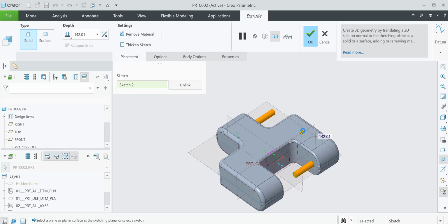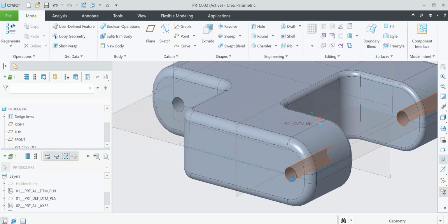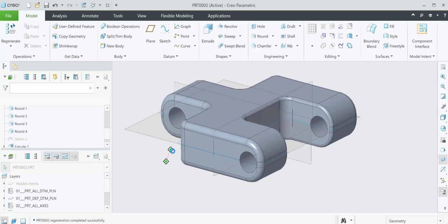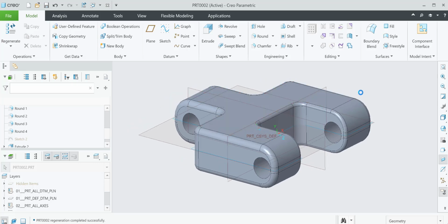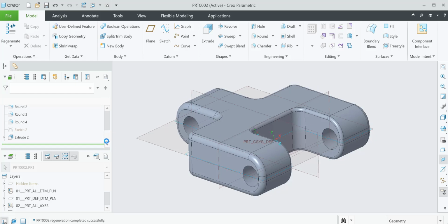As we discuss the basics of Creo, I'll just extrude it as a cut and right hold down here to say through all both ways. And that's another way to establish the holes. I like to use the hole tool because the hole tool can be redefined to have threads if necessary, which is super handy. Or you might want a clearance hole relative to another threaded hole.